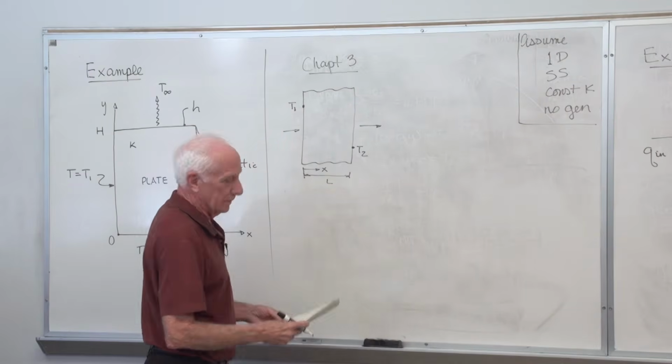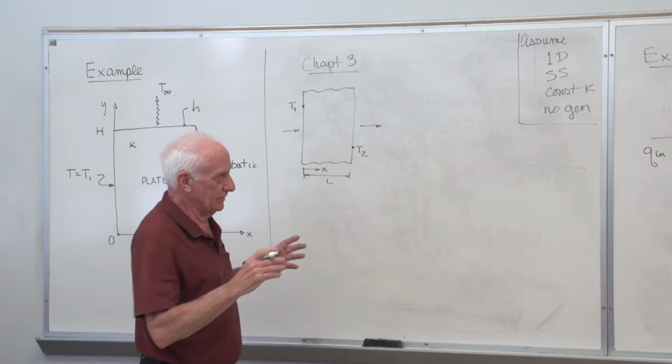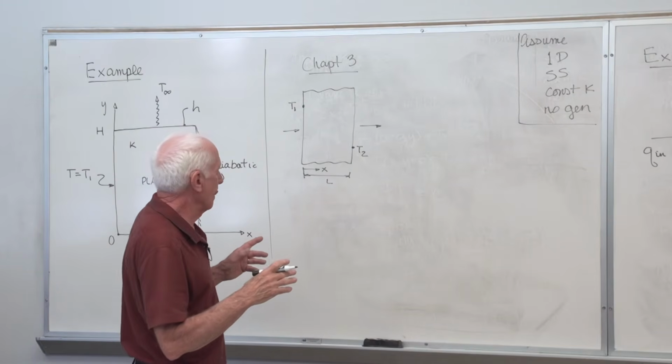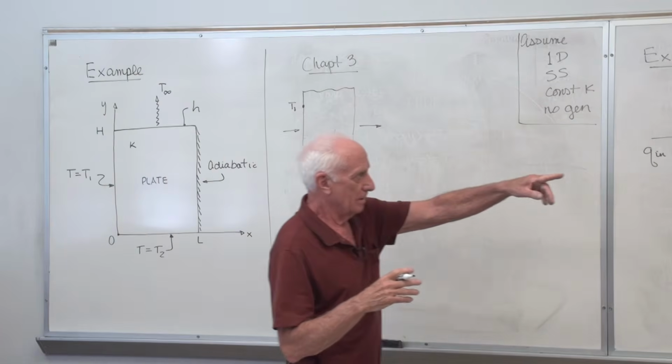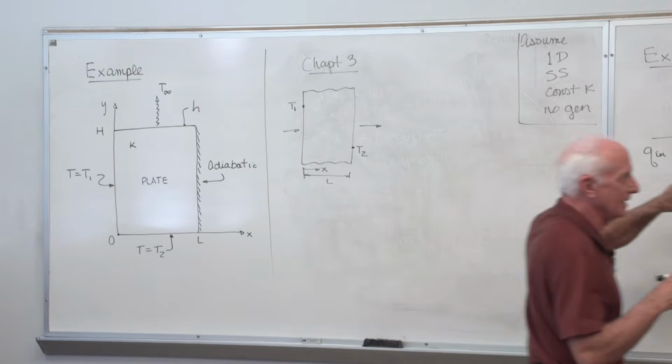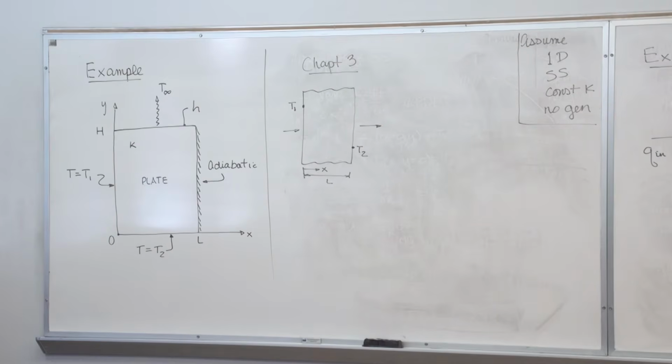Right. So now we start off and we write down the correct governing differential equation. Okay, we go over here. Follow these rules. Constant K. I already assumed constant K. This version of the heat diffusion equation has already taken care of constant K. We pull the K outside the partial sign and divide it through by K. Okay, that's taken care of.